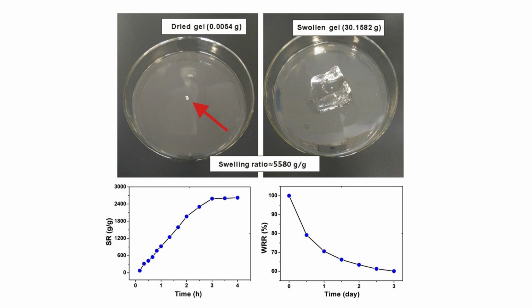The solvent is carefully removed, e.g. by drying, and the final weight, wet weight, WW, is recorded. Swell ratio equals wet weight minus dry weight, divided by dry weight. A higher swell ratio means lower cross-link density, looser network.